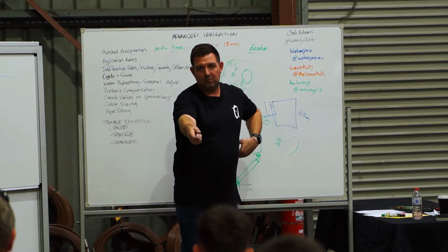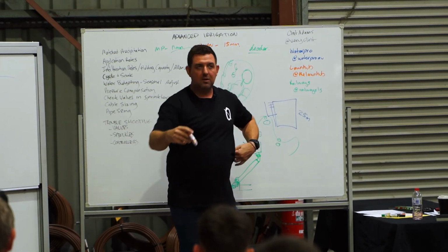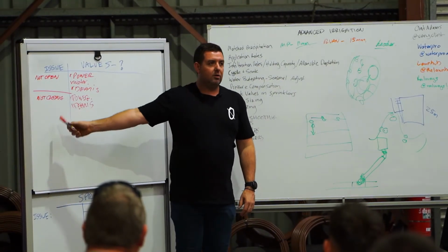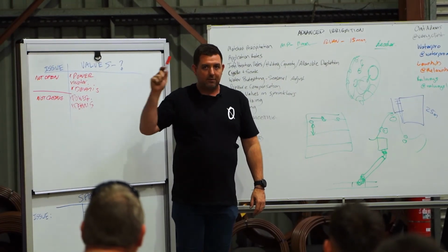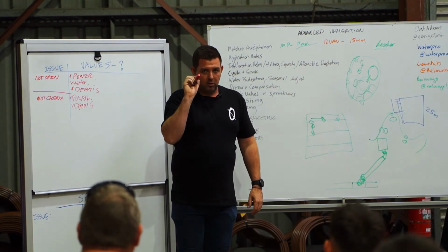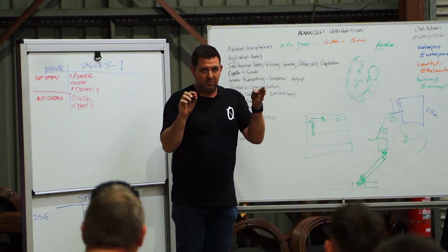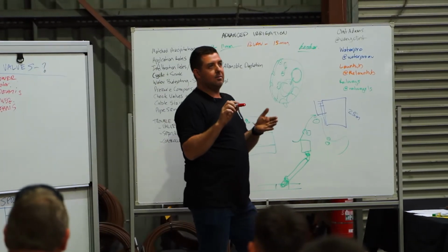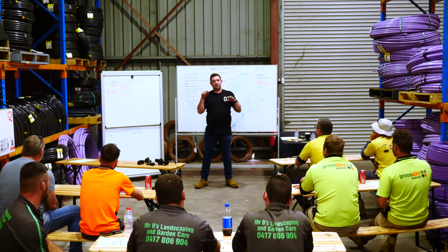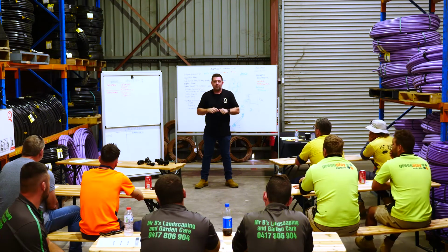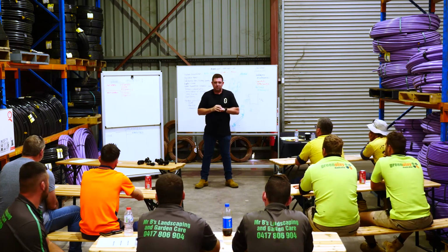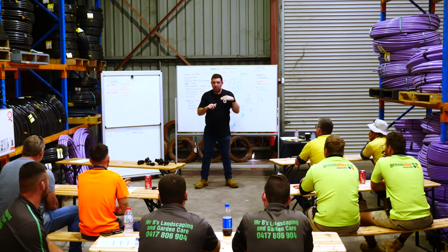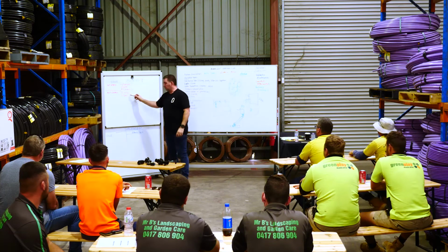You could imagine how much power it would take if it was continuously sending a pulse. Theoretically, you could have a Hunter node not close because the battery went flat after it turned on, and then it doesn't turn off. The chances of that happening would be probably higher than you winning that bloody house at Henley Beach, or lower. Anyway, you get the point. If a battery operated valve is not shutting off, it's very unlikely that it's because of the electricity not turning it off, and you would start referring to all of these other things.